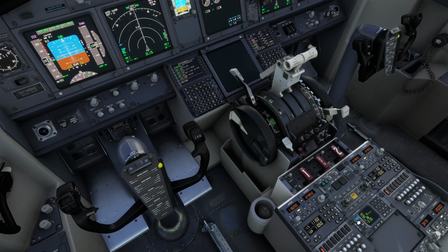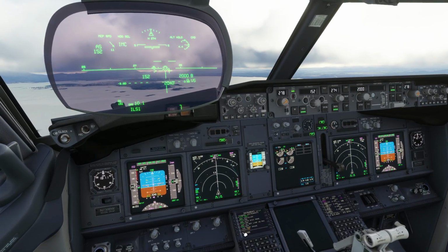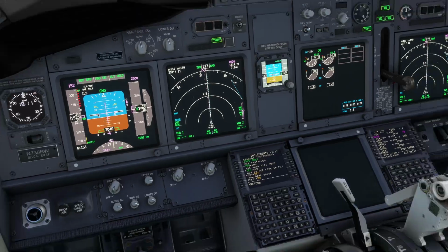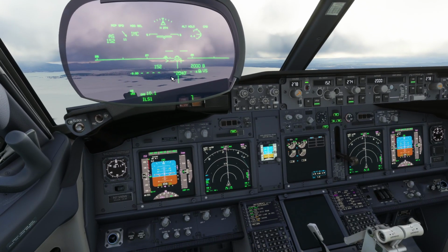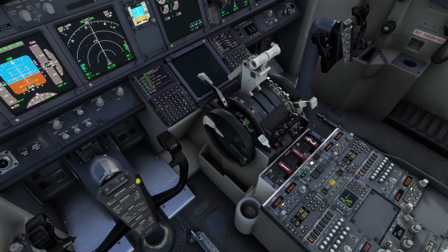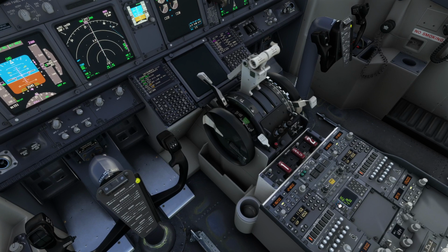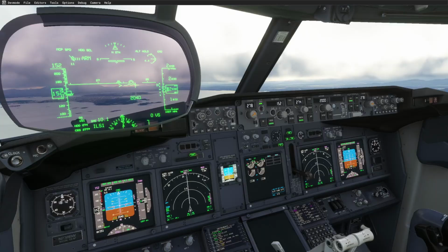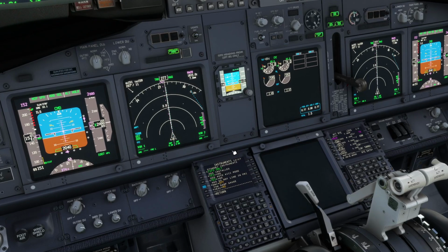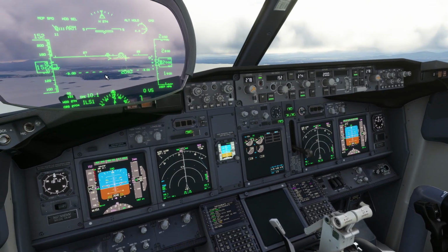If you are in a different mode like the IMC, it does not change. You can have this to on or to off, and it doesn't go away. Right now we have AIIGS glide slope reference line in primary to off, but you do have the reference there because you are not in primary mode, you are in IMC mode, as you can see here, IMC. So anytime you go to primary to have that line, note we are in primary now, and to have that line you need to have this option to on.